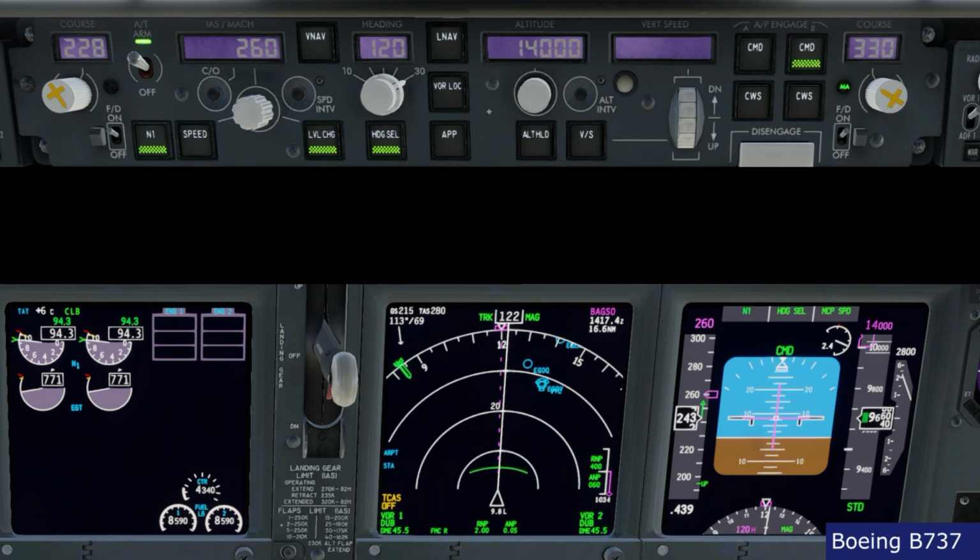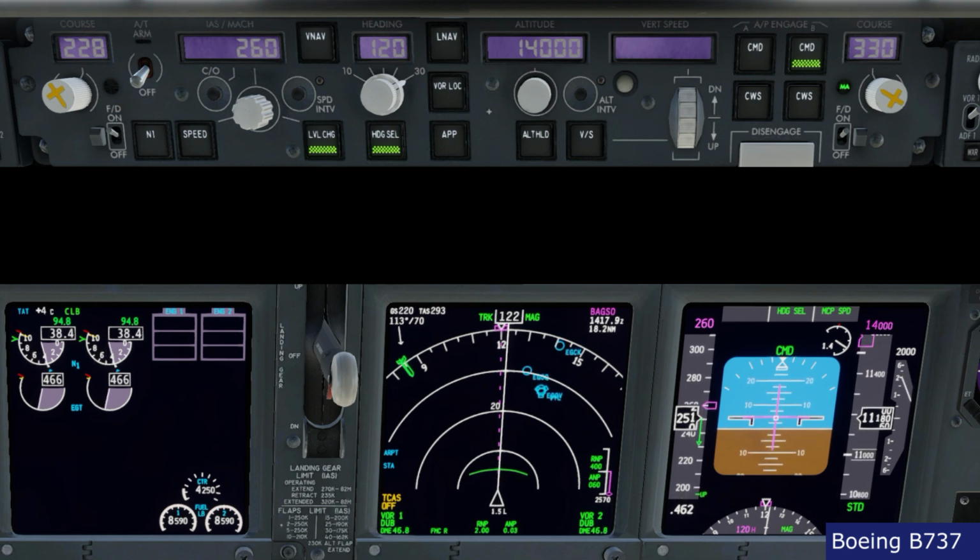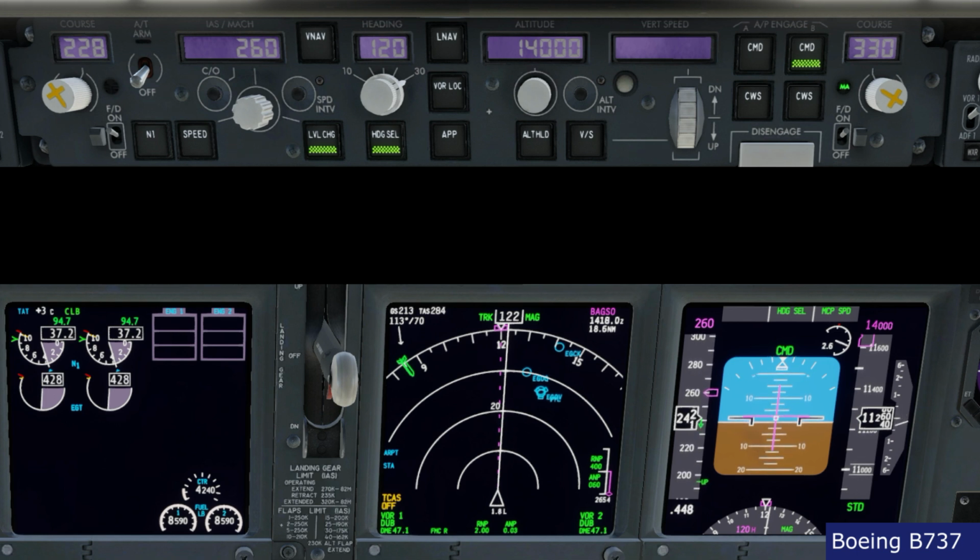Now what happens is that sometimes you are in manual flight with flight director, and the instructor asks you to make a climb. So you will ask the other pilot which vertical mode you want. For example, you will ask for level change. Now if you ask for level change and you are in manual control of the thrust, as I did now where I disconnected thrust, if I close the thrust lever or if I don't give enough thrust, what happens is that the speed, as you can see, is decreasing, and the aircraft now has to descend in order to recover the speed.